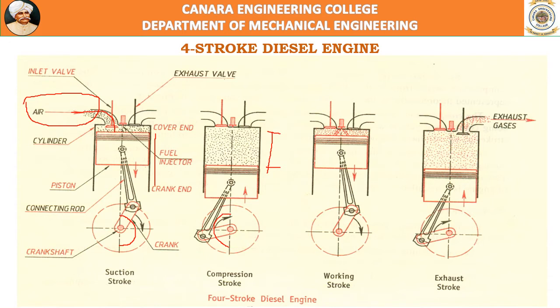The compression of air takes place. In the previous case, the petrol engine, it is compression of air and fuel mixture. Here only compression of air takes place during the compression stroke, during which you observe both inlet valve and exhaust valve are closed.